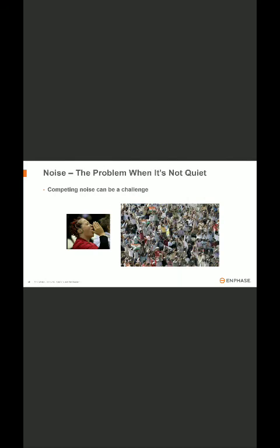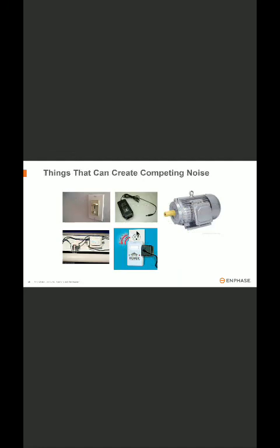Then definitely the noise. The high noise floor can be the result of heavy motor load, dimmers, dimmer switches, CFLs, UPS, test controls, plug-in things, home automation systems. These are a few things that really induce noise in the circuit. So definitely we or the users have these kinds of devices in their homes. But that's why it is always recommended to connect the Envoy on a separate circuit where we don't have noise inducing devices. These are a few examples of noise inducing devices.